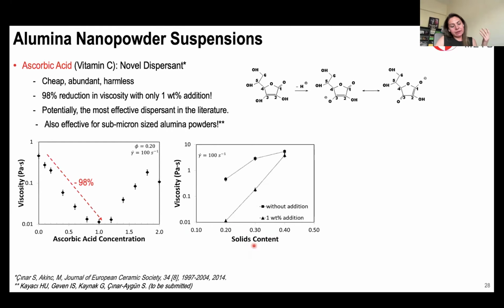So, okay, up to now I only talked about those layers, but we also have interparticle interactions. If you are working with highly loaded suspensions, and if you have very small particles, or very limited interparticle distances, using large molecules as additives is dangerous because you may face bridging issues.